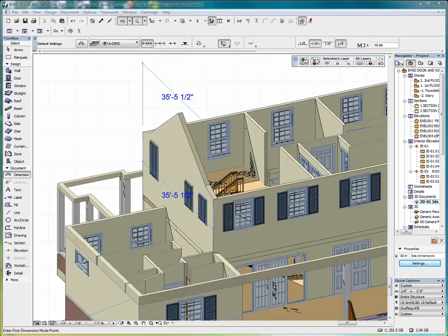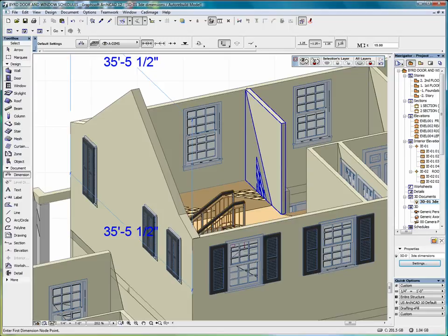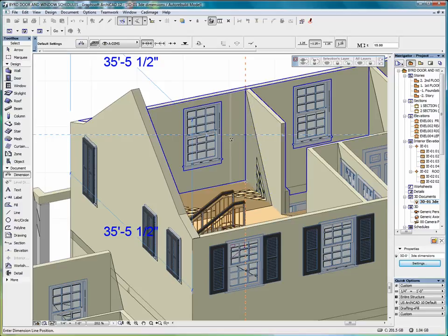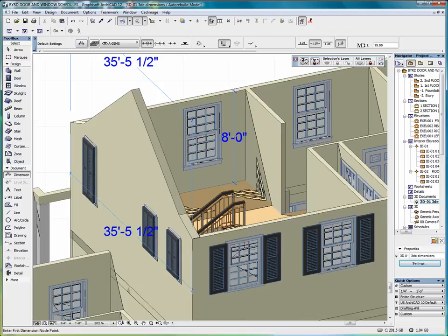Say we go into an inside corner here, and we want to dimension the height of this wall. So we place our first 2 points and we double click. Now I have a little compass that's asking us which direction we want to place this dimension. So we click once with the magnet on that wall and click again, and now we have a dimension on that wall.